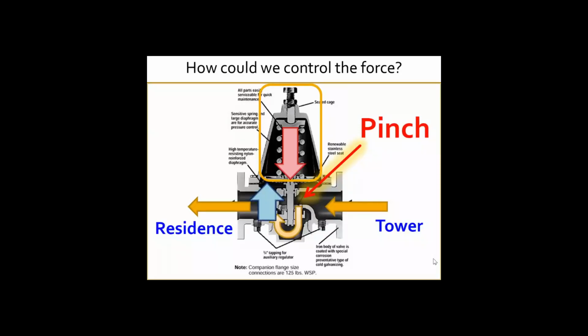And when they're equal, then the valve is going to be closed. So this is adjusted, the bolt on the top of this regulator is adjusted until the water gauge at your home entrance equals roughly 45-50 pounds PSI. That's how you adjust these regulators.